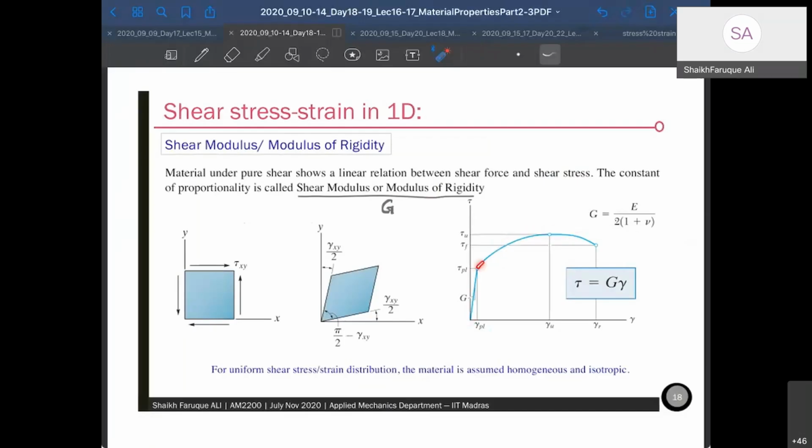Sometimes it's not this curve, sometimes it becomes very flat based on the material, and then it can go along very long, because when you rotate a rod, the plasticity becomes large; you can keep on rotating more than 360, maybe double, so around 720, and then it can break, right? So this flat part is very long, whereas the linear part is very small. But again, you have a linear zone, and here is where Hooke's law is followed, right?